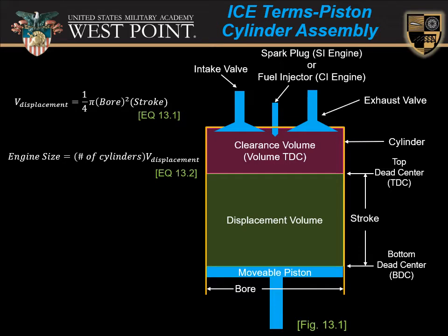Don't confuse that with the maximum volume. The maximum volume, or the volume bottom dead center, is equal to this displacement volume plus the clearance volume. This is a common error. This is equation 13.3.